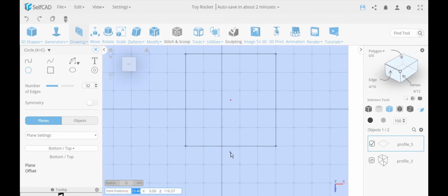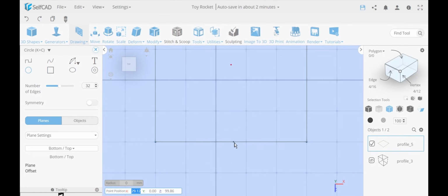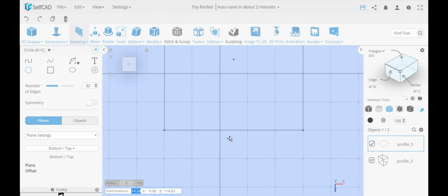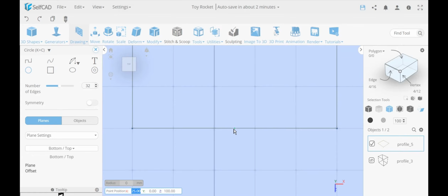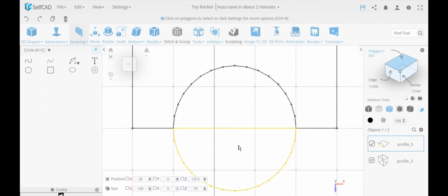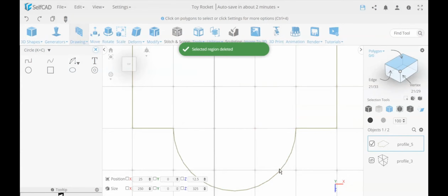So first of all, I want to show another thing here, that this will allow you to snap to center points. You see, you have nothing here to snap to. I'm just snapping to the center line. So everything you have, either the center of the mesh gives you this red dot, or any line itself. It doesn't show you a dot, but if you hover on it, it will show you a green arrow. So I can center to it. And now I'm going to make a big circle. Okay, doesn't matter. And I'm going to cut this out, or actually remove the inside part. Okay, something like this. Okay, now why not make this, yeah, why not? Doesn't really matter the example. So I'm going to show something like this.